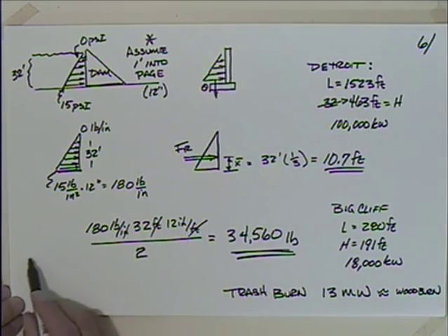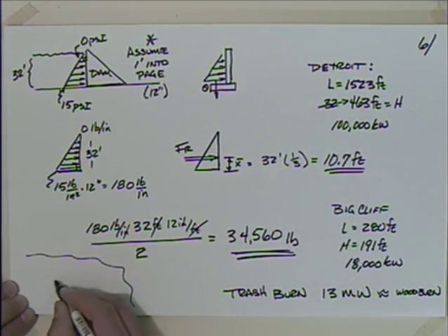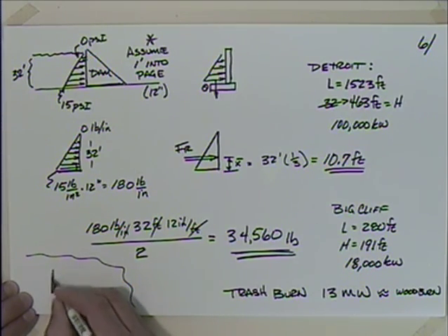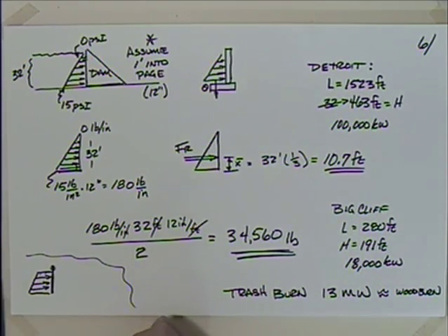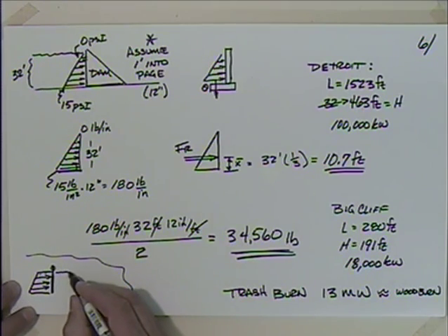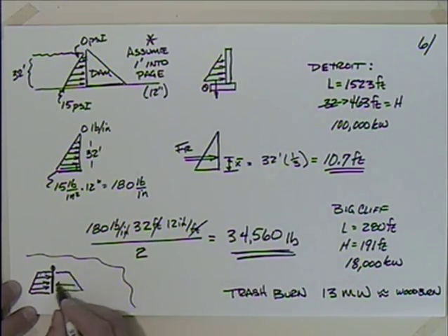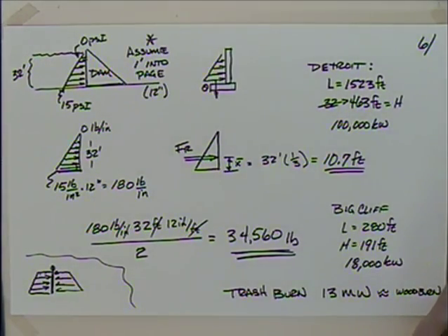Because if you look at, we've got enough spot here. Let's say you look at the car door here, and we'll say this is your car door. I'm not sure which is up anymore because it's fallen in, but there's the hinge, and you have a pressure distribution, which maybe looks like this, depending on how it's oriented in the water. You have thousands of pounds on it. Your only hope is to get an equal pressure distribution over there by letting the vehicle fill up. So you let it fill up with water, which is probably not good for your habitation of that anymore, but hopefully then you can get the door open quickly and get out.